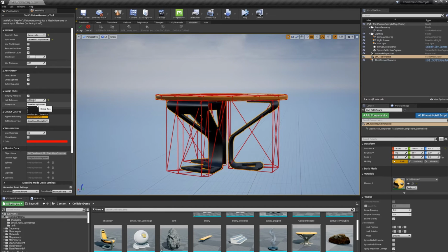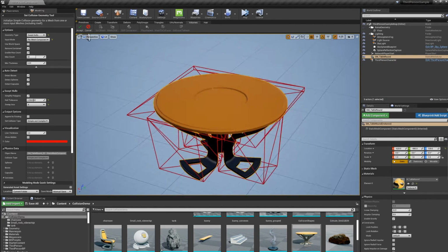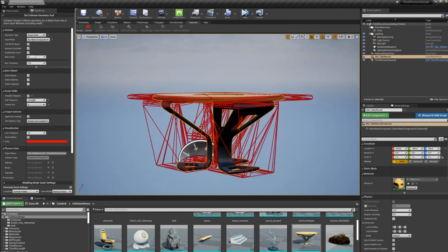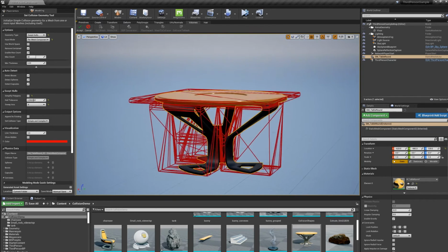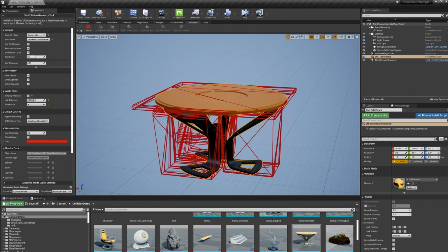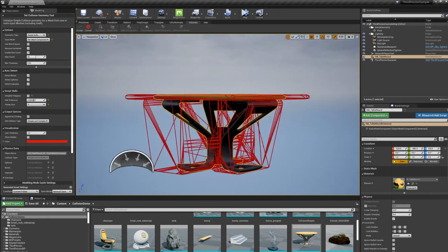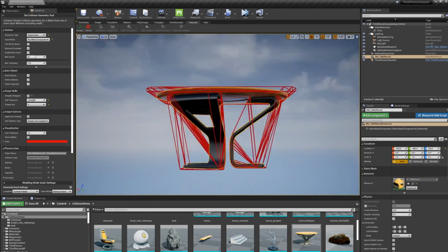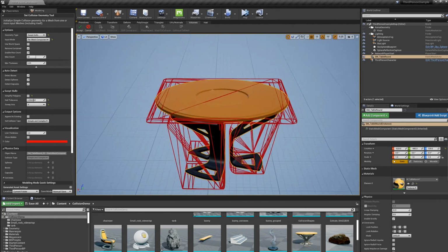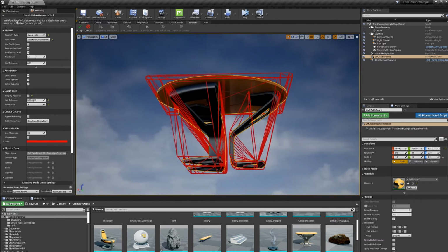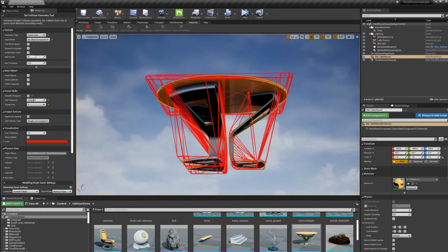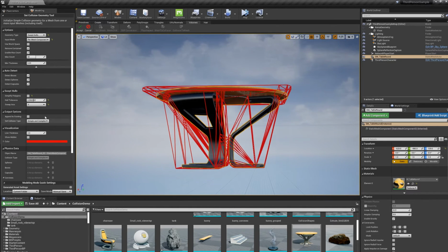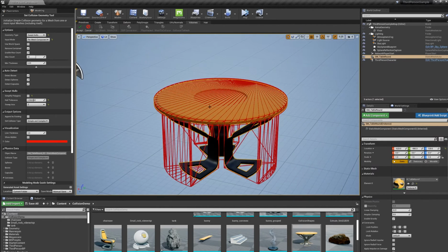So you can sweep along what it considers the X axis. You can see down in the bottom left, we've got X, Y, Z. It considers those three axes in the local coordinate system of the shape. So there's sweeping along Y. You have to find the right direction, but from this direction, it captured the curve here of that piece. And Z is straight down.